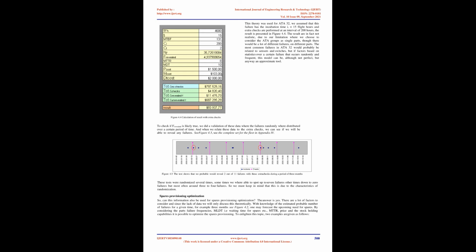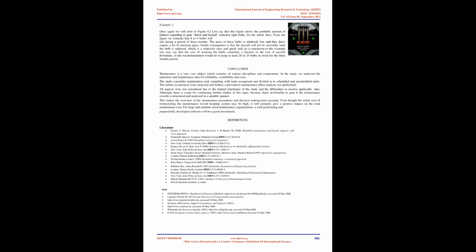Spares provisioning optimization. So, can this information also be used for spares provisioning optimization? The answer is yes. There are a lot of factors to consider, and since there is a lack of data we will only discuss this theoretically. With knowledge of the estimated probable number of failures for a given time, for example 3 months, see figure 4.2, one may forecast the upcoming need for spares. By considering the parts' failure frequencies, MLDT, i.e. waiting time for spares etc., MTTR, price, and the stock holding capabilities, it is possible to optimize the spares provisioning.